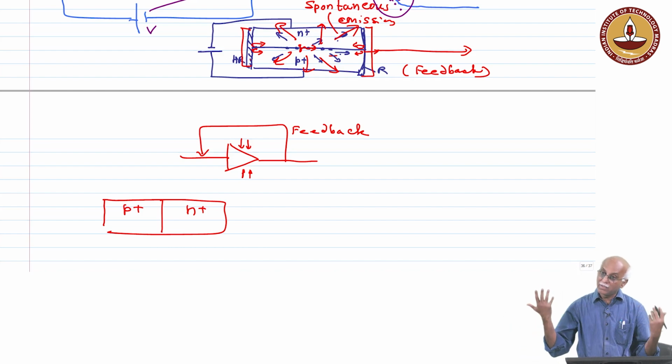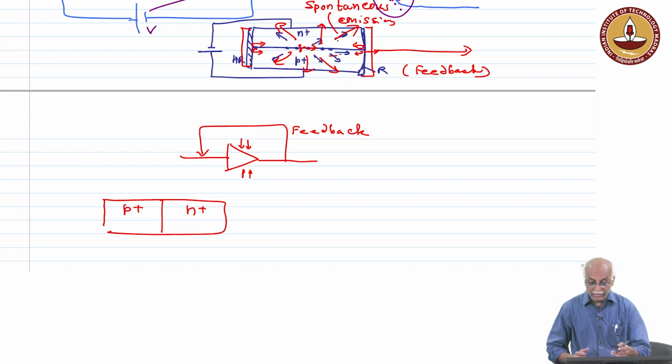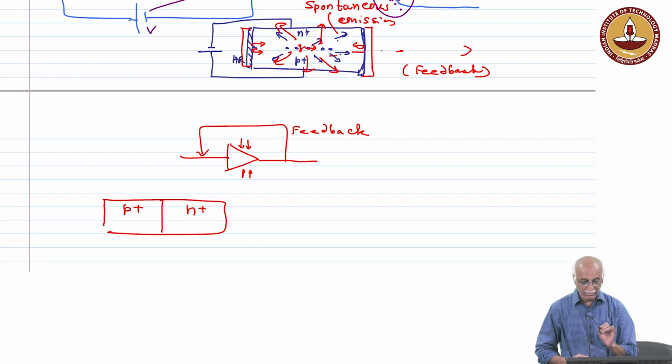Those photons are becoming a loss for us. And in order to generate laser output, we need to feed in a certain amount of voltage to provide enough photons along this direction, and accordingly the amplification takes place. Now, indirectly the threshold for this lasing operation is large when it is a homo junction material.